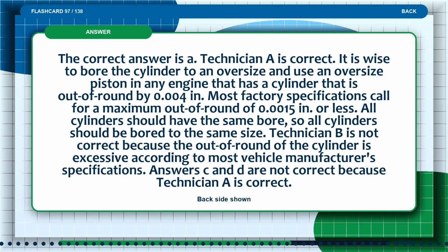The correct answer is A. Technician A is correct. It is wise to bore the cylinder to an oversize and use an oversized piston in any engine that has a cylinder that is out of round by 0.004 inches.